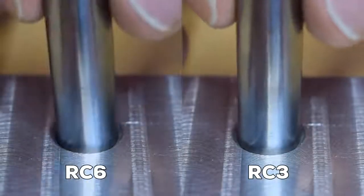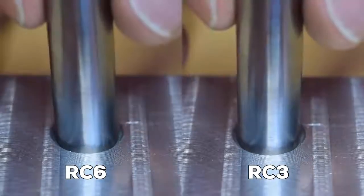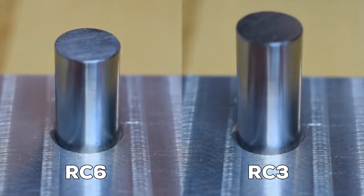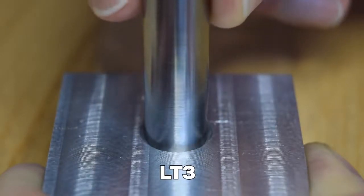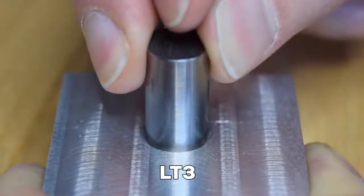Here's a comparison of the two running fits. The RC6 has some perceptible play, while the RC3 has almost none. RC3 and tighter will precisely align components, but can still be assembled easily by hand. This next type of fit is called a transition fit, and it requires a slight amount of force to assemble and disassemble. However, there's absolutely no play once the pieces are assembled.